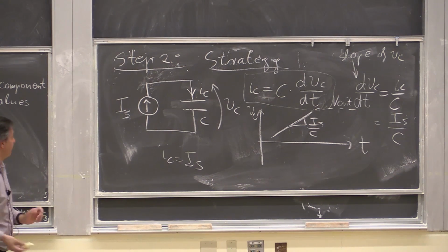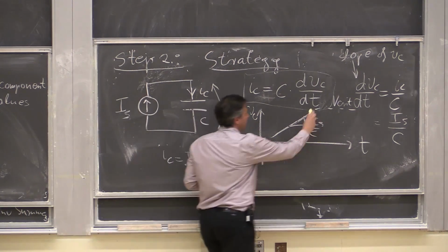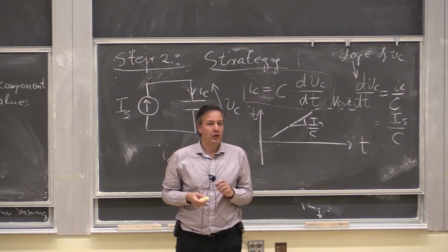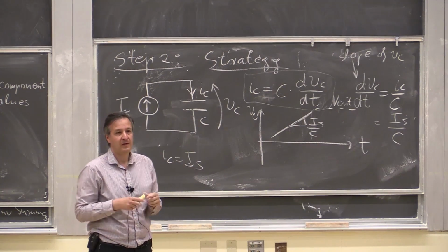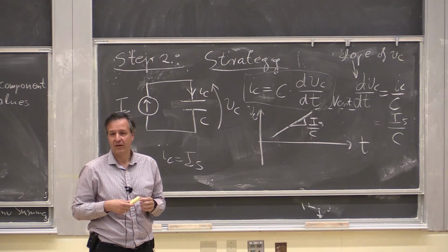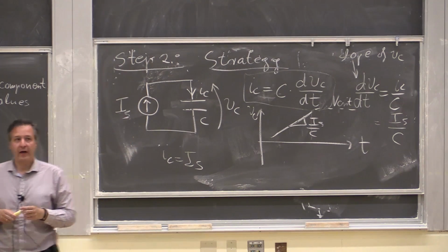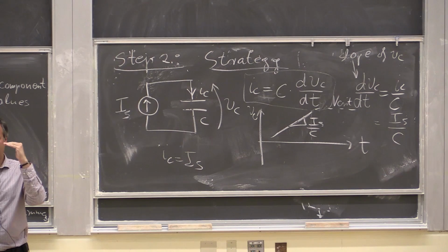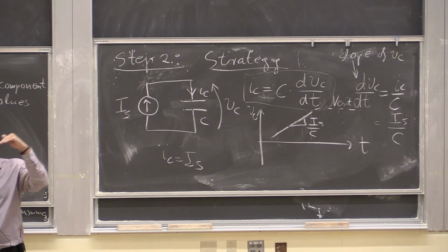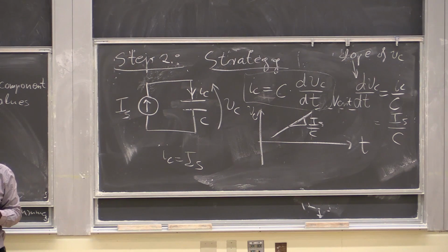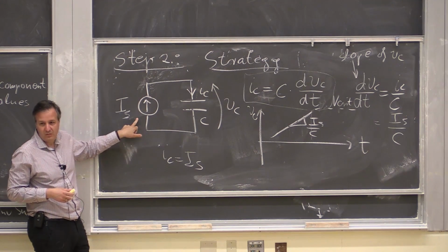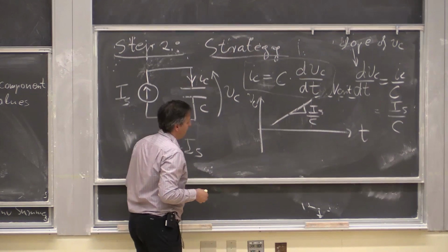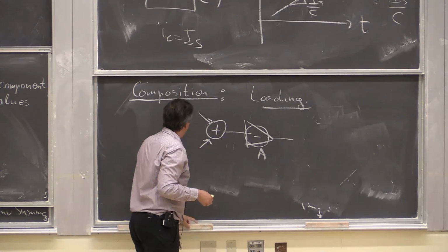So if I switch it to ground, I will just do abruptly something like this, right? So yeah, you're right, you can do that. That's okay. But I'd like to do a more gradual thing. Charge sharing will just instantly create some change. I want to gradually ramp it down, just the same way it came back up. Yes? Yeah, so I need to switch the polarity of this current source. Right. So I can do it by, for example, adding a few switches.